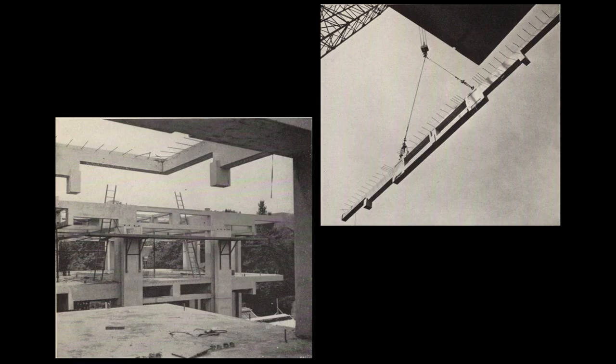Each of the individual structural elements here are reinforced concrete, okay? Each of those horizontal joists, which you can see hanging off the end of the crane up there. Yet they are all, first of all, precast. Precast meaning that they were formed elsewhere and then shipped to the site. They were also pre-stressed, which means that there were tension rods which were affixed to the formwork for these, and then those tension rods are pulled taut.